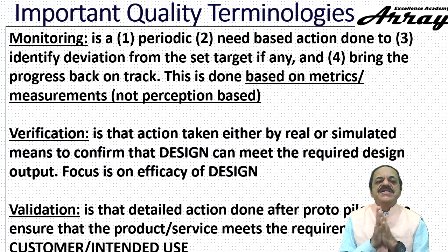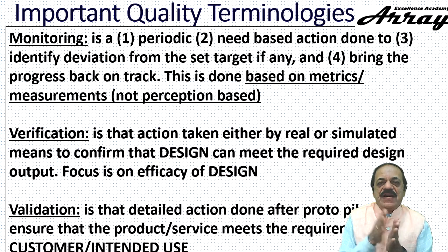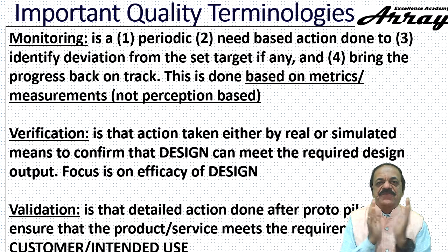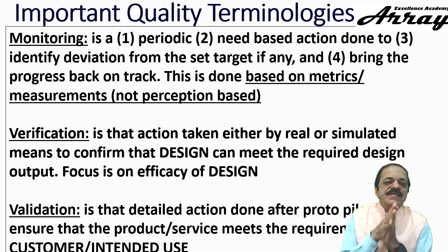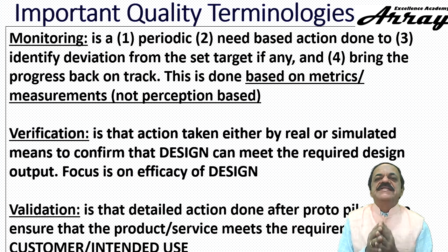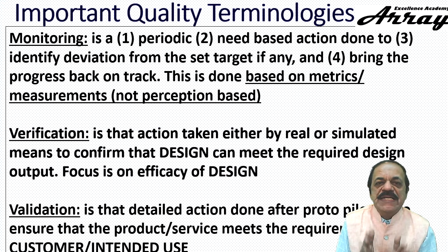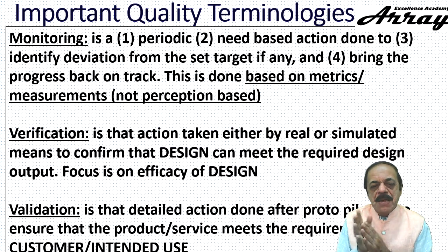Now we come to validation. Validation is a detailed action and cannot be done in simulation mode. You need to build a proto pilot, meaning at least a first sample piece, and do a detailed check to see whether this product can meet all the requirements of the customer if it is a custom-built item, or all the requirements or intended use of the market. Because if you do not, your competitor will do better and occupy the market.